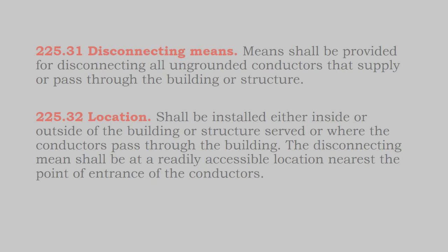Well, you may need to have a neutral be fully connected throughout the entire system in order for that kind of automation to occur, so that you can monitor the status of the grid versus the status of your generator versus the status of your battery bank.